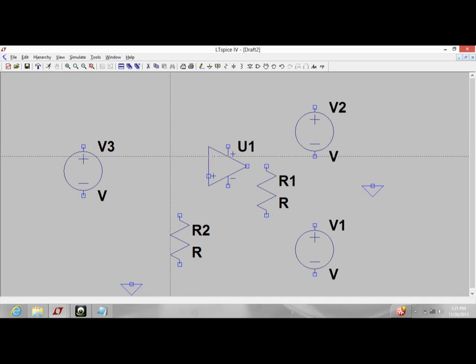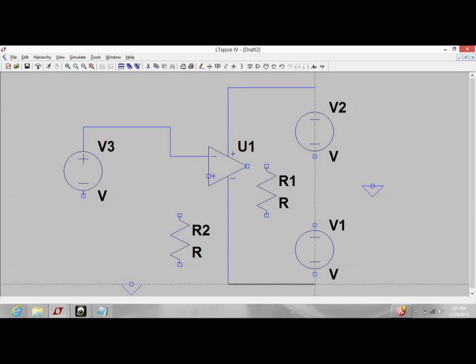First of all, connect this to the input, then I'll provide this with the plus VCC, and now a negative voltage. I'm providing them with a common ground. You can use different individual grounds for both of these voltage sources. I'm connecting a resistance between the output terminal and the non-inverting terminal, and a resistance between the non-inverting terminal and the ground. Okay, this is done.